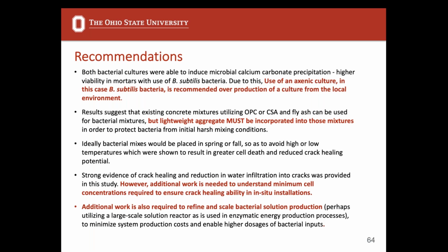So my recommendations are, if you want to use this, you might as well choose a pure material. The B. subtilis had a little bit better results in the concrete than the soil sample did, but either one will work. You must incorporate lightweight into your mixes. And then ideally you would plan to place these mixes in spring or fall so that they have a little bit of time to exist in a comfortable temperature range and prevent the bacterial cell death that could occur quickly. However, overall, I cannot recommend using this in your city or town or state roads at this time.